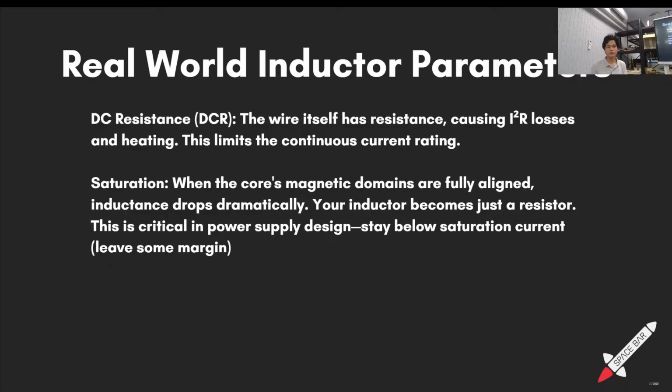So we call this the saturation current, and just like voltage rating, this is a current rating. Do not approach the current rating too closely when you are designing with an inductor. For example, on one of my circuits, I needed a saturation current of 5 amps, and I had to choose some stupid giant 10 amp inductor, and it's huge, and it's very upsetting.